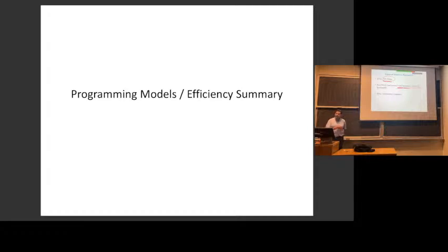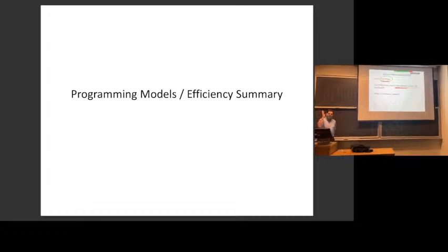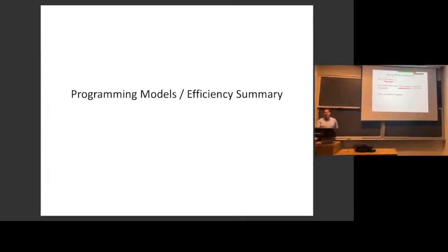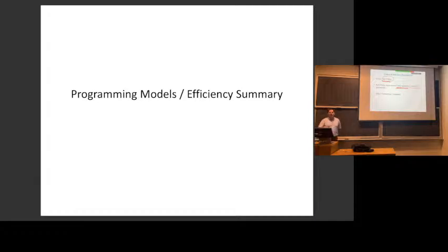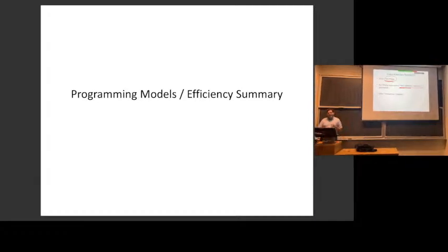The compute units on the FPGA are fairly simple, right? Block RAMs feeding a multiply accumulate unit. What you'd like to do in an FPGA is actually build a pipeline. So you'd really rather have this compute unit directly feeding that compute unit, directly feeding the next compute unit, and only accessing RAMs maybe at the very input. If you can do that, you could actually get significantly better efficiency than what they said. So that's where you get into the more complex aspects of your application. But there are classes of applications where these numbers will tell you what to do. Does that make sense?